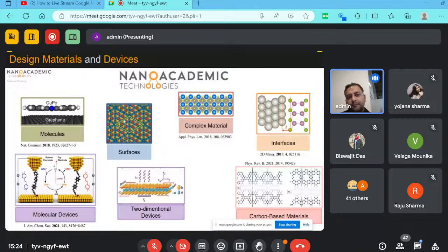Surface where you can define some 100 plane, 111 plane, 000 plane, or any surface plane. You can also define some different complex structures. You can define some lattice parameters, some alpha, beta, gamma, ABC value, rhombohedral, hexagonal, tetragonal, triclinic, or from different space group, 1p1, 2p1, 3p2, different space groups you can select, and you can create different kind of lattice structures.